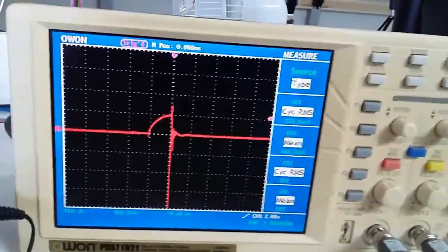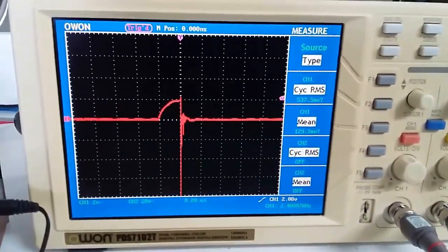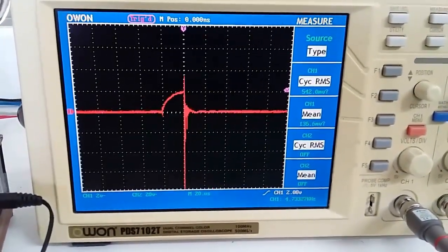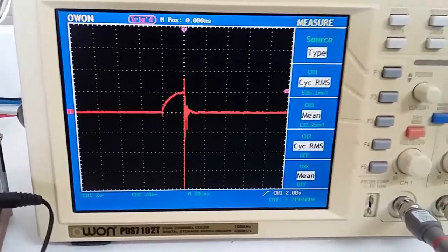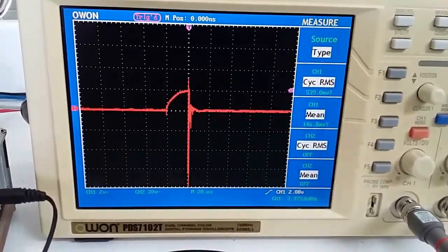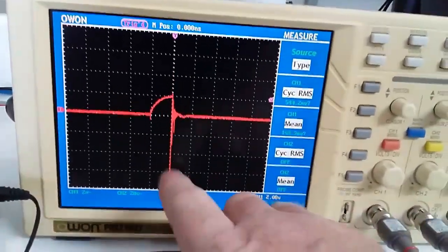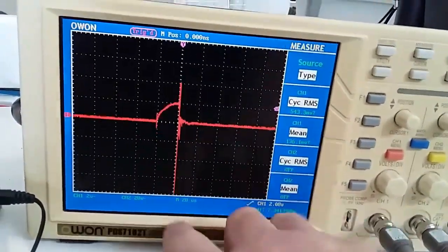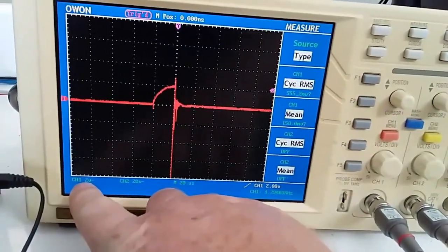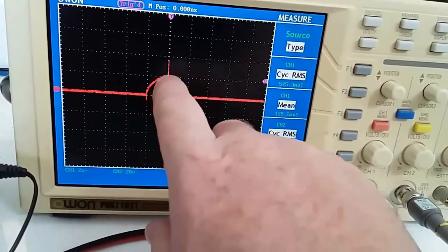So we could say, because of that time division, which is 20 microseconds, okay, so we're looking at a very, very short pulse there, 20 microseconds for the run, and also, I beg your pardon, no, it's not, it's 2 volts for the rise. Okay, so the run is 20 microseconds and the rise is 2 volts. Alright, so we're looking at a rise over run, and that's what the input coil is doing.